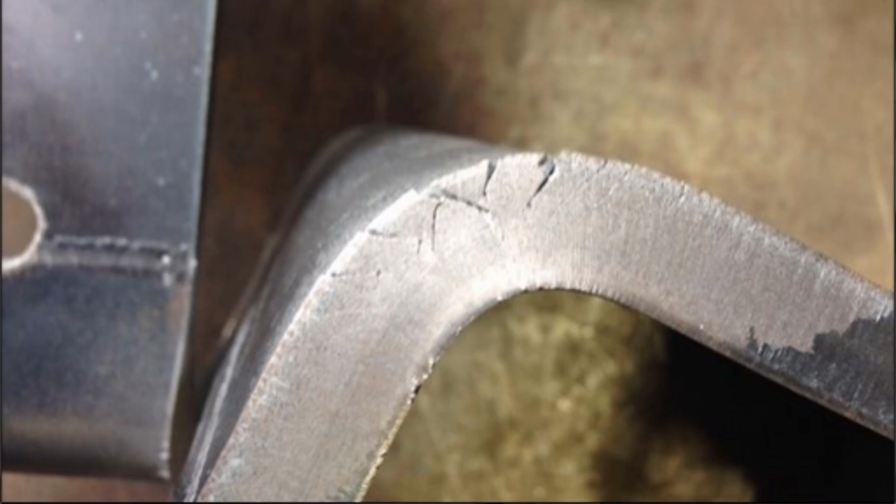The purpose of a minimum bend radius is to protect the material during the forming process. Let's have a look to see what happens if our bend radius is too small. Here, in this example, we have a plate of approximately 3/8 of an inch thick, constructed from ASTM A572 grade 50 steel. The inside bend radius was too small for this application, resulting in the plate material tearing or cracking during the forming process.